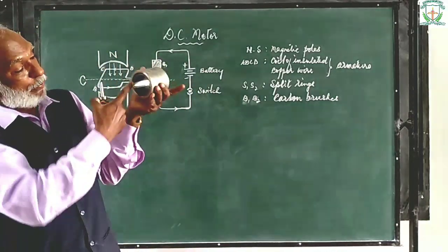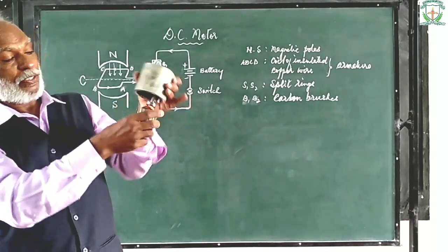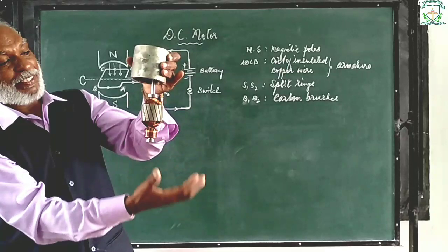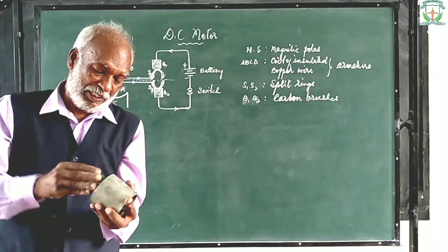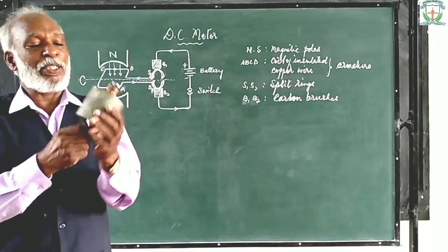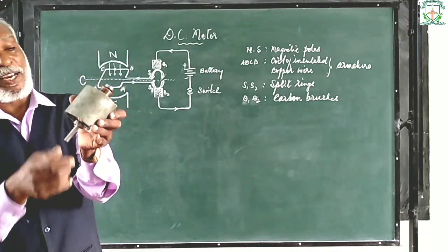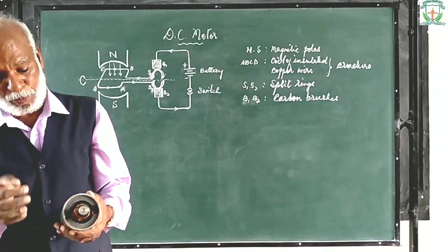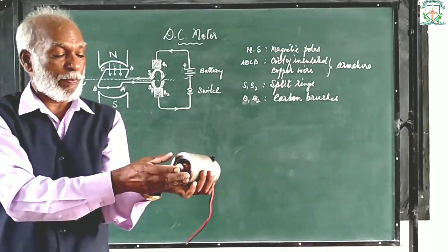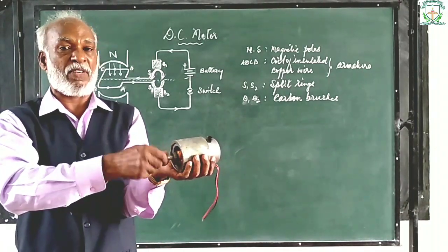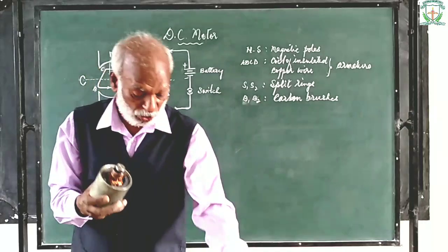See, this is one magnetic pole, this is another magnetic pole. How strong it is, you see. See, it's so strong. So, this armature is mounted between 2 magnetic poles. Understand? So, it is mounted actually using ball bearings. Here this side it will be, and this side one more cap will be there. So the armature will be free to rotate. Understand? Free to rotate.